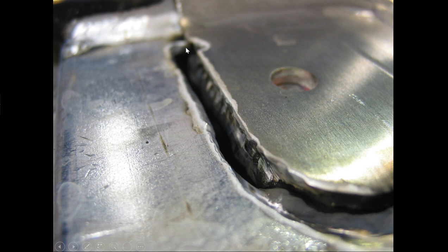And here's the other thing too. Supposing you did. Supposing, oh yeah, I'm going to challenge myself tonight. I'm just sitting here. I'm going to fix this one. Not only is there no base metal, which is what I'm worried about underneath it, there's nothing there. But we already know that liquefied aluminum, if it's not protected by argon, is going to develop all the oxide. That's what happens on the inside of these welds. It just looks like a black rocky road on the inside, and it will have no integrity.